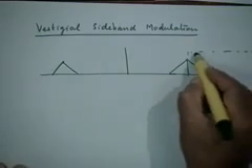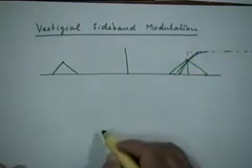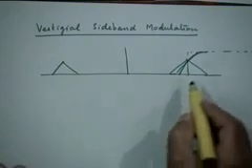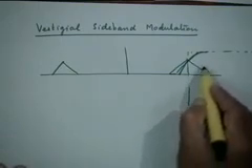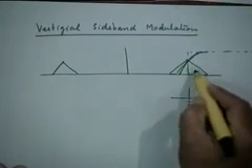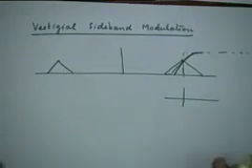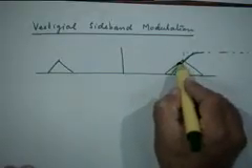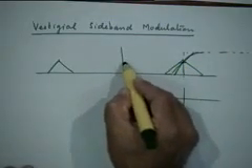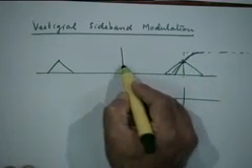Typically what will tend to happen is that even if it is a good filter, the amplitude characteristics might be like that, and the phase characteristics in this area would be highly nonlinear, because the sharper the cutoff, the more nonlinear it tends to become. So phase characteristics will become highly nonlinear, which will imply some kind of delay distortion or phase distortion of the low frequency components of the message signal. Why low frequency? Because these frequency components actually belong to the low frequency component of your original message signal.